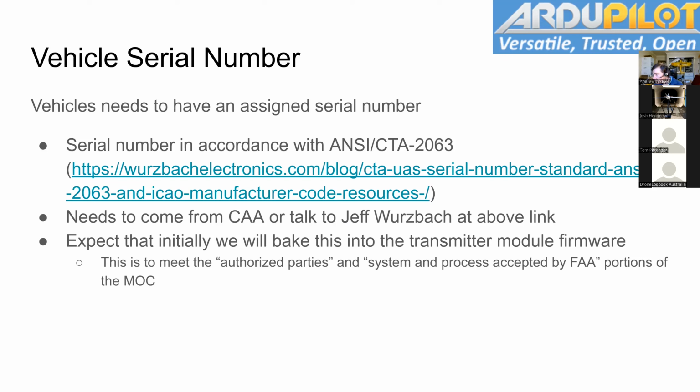We'll take the other example I gave with the different GPS. My understanding from what you said is you have to define a package of what this device includes. So if it includes a specific GPS, there's a parameter for that, and you have to lock it down. Okay. So if you have a different GPS, would you not have to have a different board ID for that? It depends. If it's u-blox, then you just set it as u-blox and you're done. It'll support all the u-blox modules. If, however, you want to use Septentrio, then yes, you will need a different GPS type.